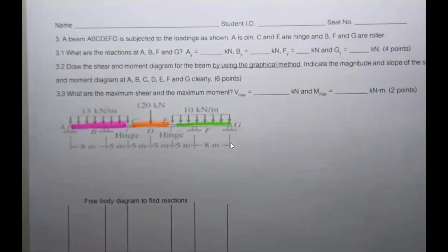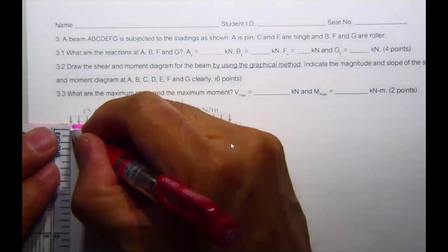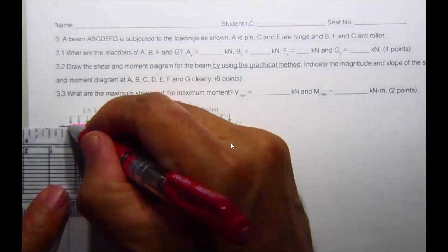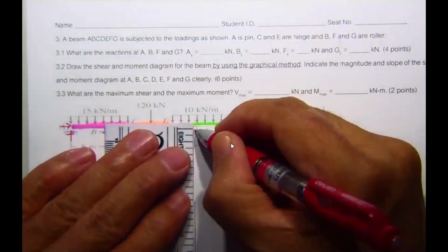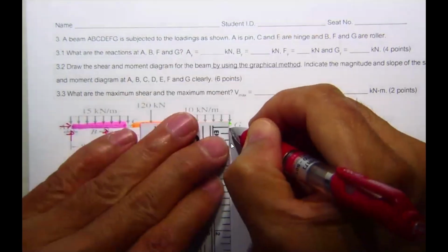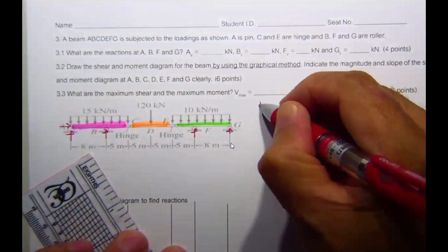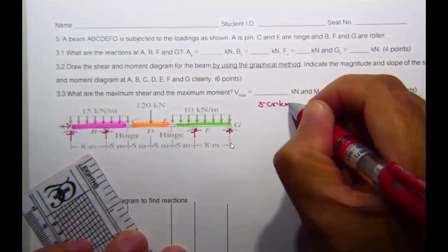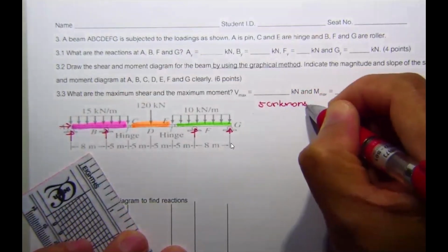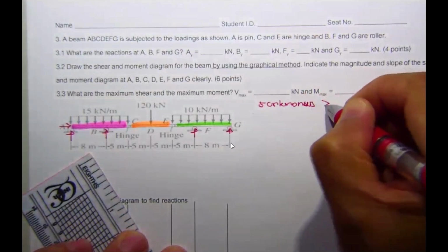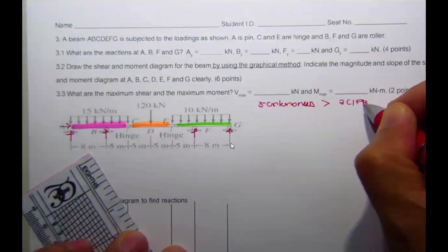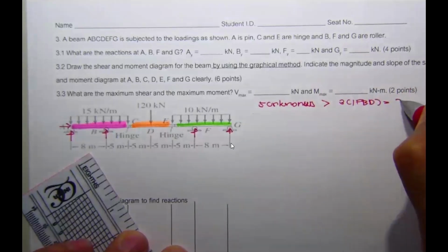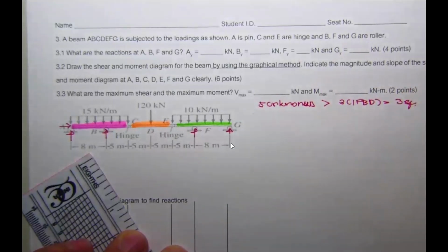If we determine the reactions, this is pin 1, 2, and 3, and 4, and then 5. For the free body diagram, we have 5 unknowns, which is larger than 3, since one free body diagram gives 3 equilibrium equations.